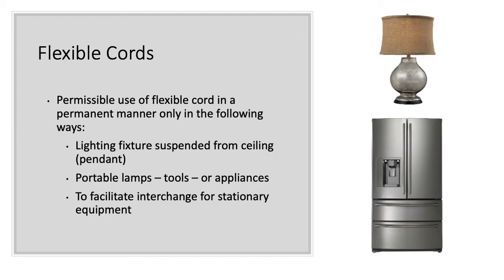All right, so a little bit more on flexible cords. Obviously, the main purpose of them is to reach objects and appliances that are far away from the outlet. The problem with them is they're not necessarily designed to be in permanent use, especially in conjunction with outlets or power outlets like power strips. So the problem is they heat up over time, they degrade, and we just kind of leave them alone. You don't think about them after you plug them in.